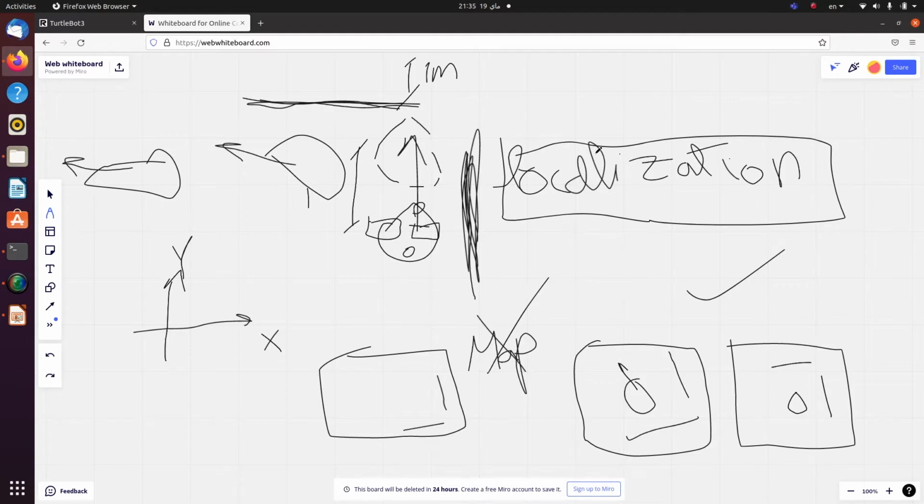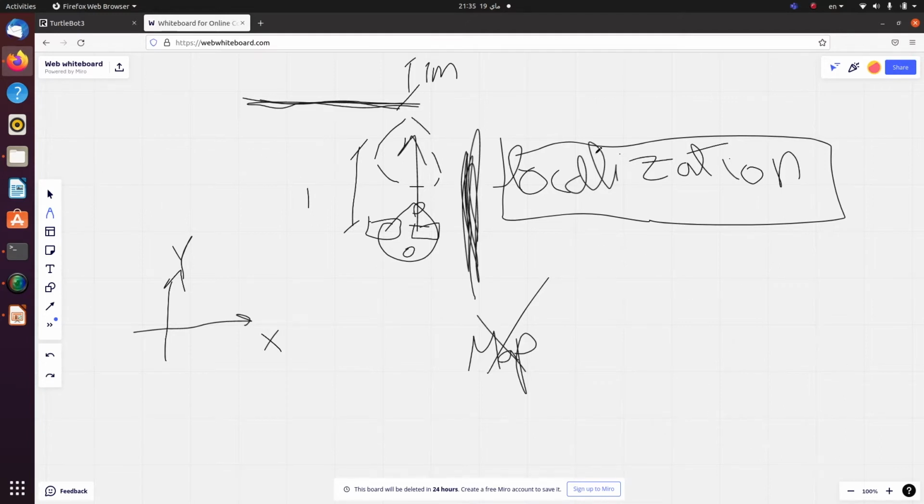So let me just play some stuff. And the problem of SLAM is a complex problem because you're trying to get localization from mapping, which does not exist, and get mapping from localization, which also does not exist. So this is crazy, and it's a complex subject that would require a separate lecture on its own. But let's just say that by fusing the data coming from different sensors, we could obtain a sensor fusion paradigm, and you can determine the pose of the robot, right?